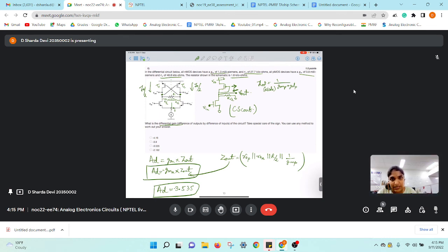So see, because you cannot keep this diode connection to be floating, right, when you are going for half circuit analysis. So what is the better way to put it down? So we can make it normal diode connection, because it is safe to say, right? Because now when you are seeing an ideal biasing condition, you can clearly see that both these terminals are at same potential.